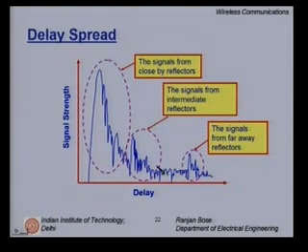But if your frequency increases, in other words, if I were able to send a much narrower pulse, then probably I can resolve each one of the multipath components. If I can resolve the multipath components, I can extract some more information. So I can work better and obtain inherent immunity against multipath by resolving the multipaths, if I have very narrow pulses. But the delay spread will not change.